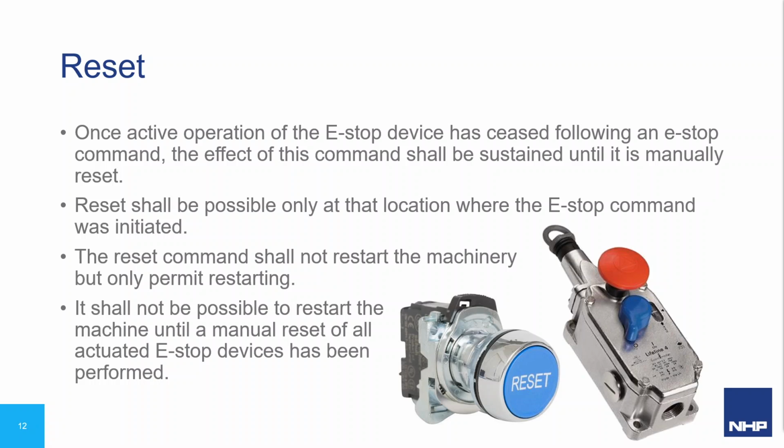There is a difference in the wording between reset and restart. The reset is to clear the conditions back to a default state. In the case of the e-stop, this is to revert it back to its unactuated state and permit power to the control circuit, if this is the normal case. Restarting, however, is the actual startup of the machine, putting it back into a moving and operational state.